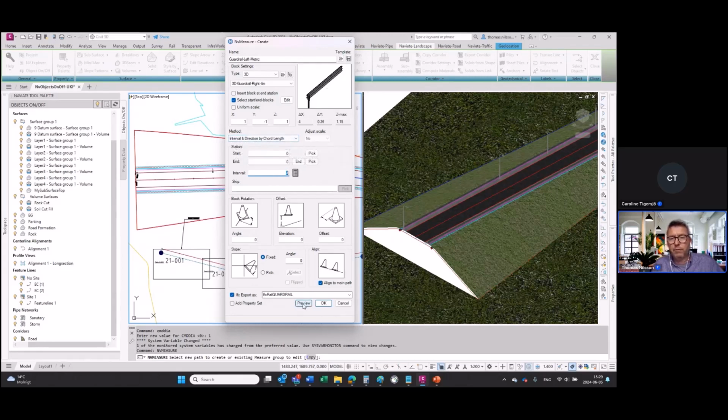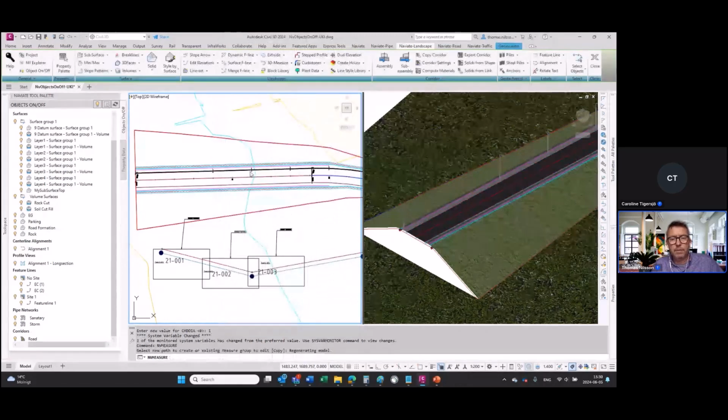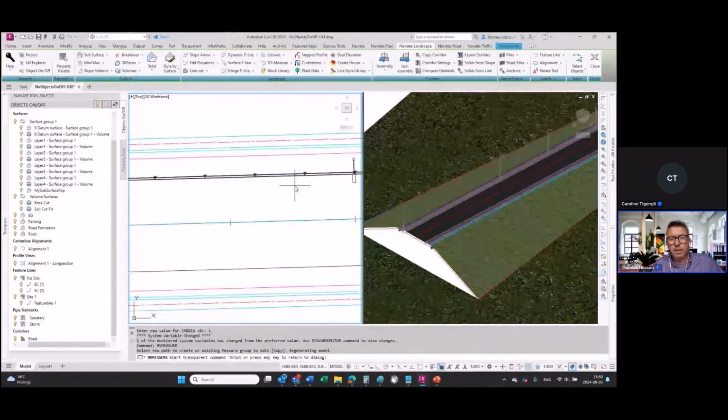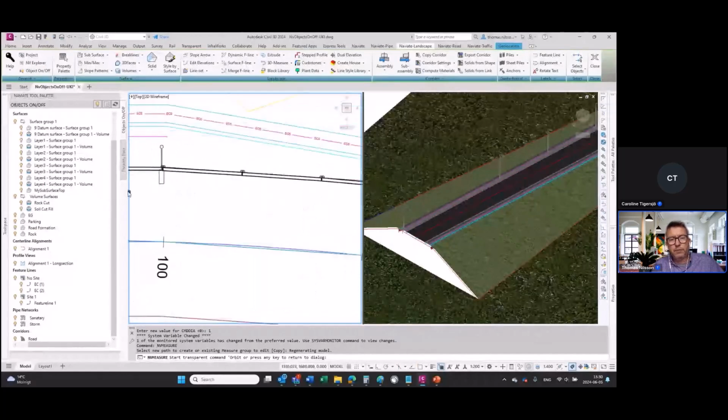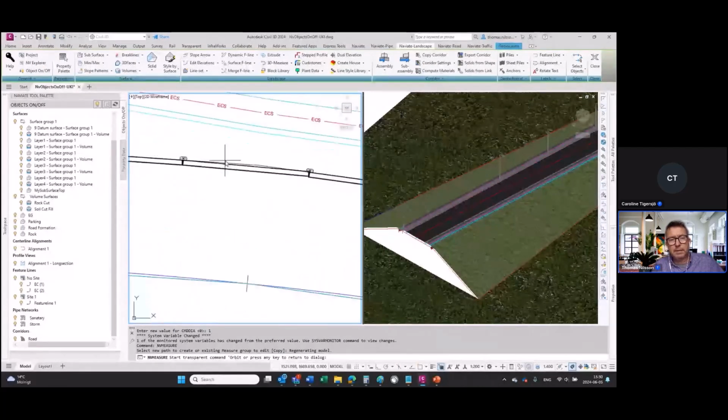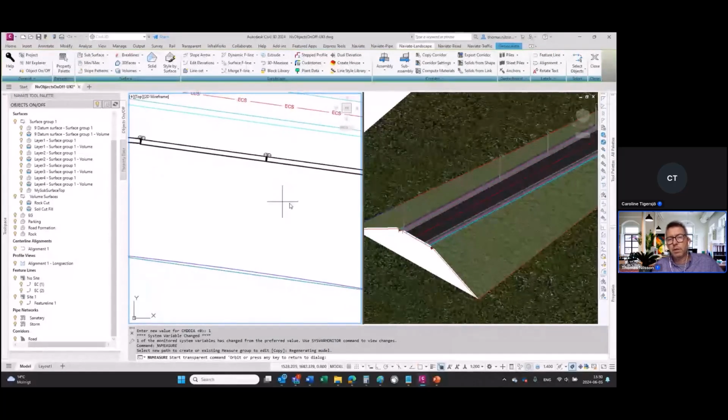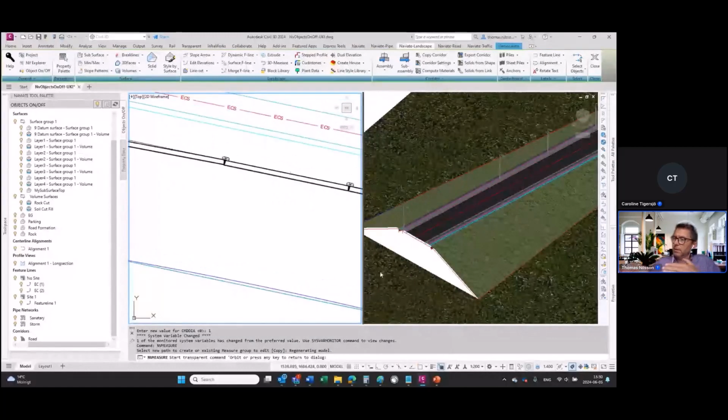I'm going to do it for the whole road first. And if I zoom in, you will see these are the guardrails. From the top, we can see that one actually is going across the feature line to meet the next insertion point. So we kind of insert it seamlessly along. It's not 100% because this road is going downwards, it's turning.